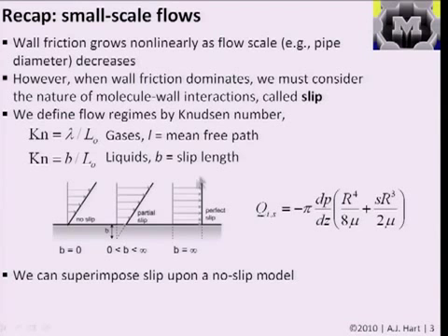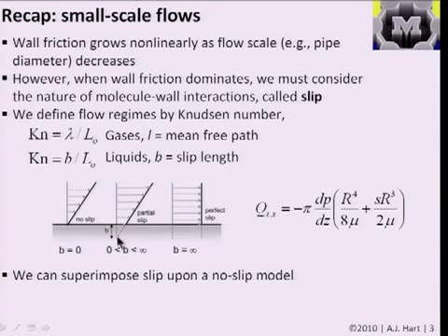And in the case of liquids, we defined what's called the slip length, and we related that to, for example, where the velocity gradient would lead to a velocity of 0 beneath the wall if you extended it by linearization. And we define that distance b as the slip length. Then in the case of no slip, the slip length is 0, and typically we have some finite slip. And if there were perfect slip, if there were absolutely no friction, or the molecules between the wall and the fluid didn't interact, you would have an infinite slip length.